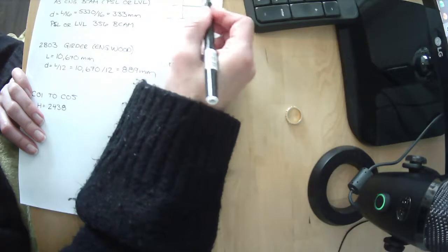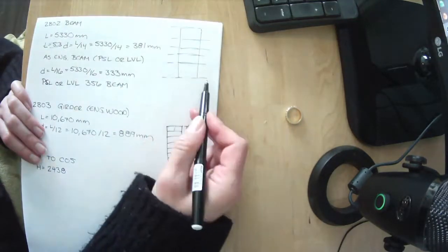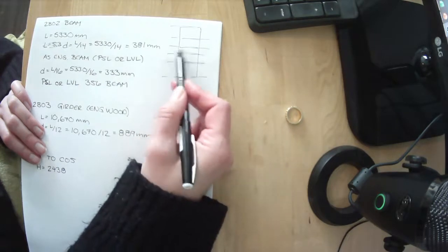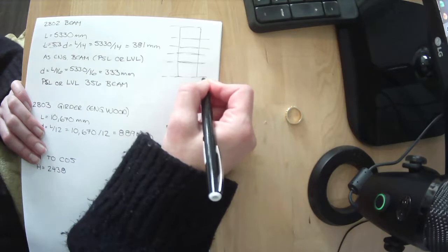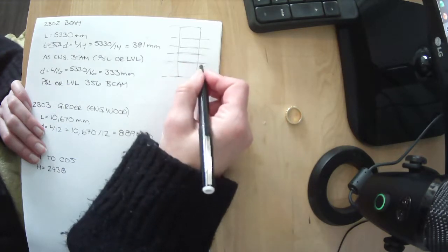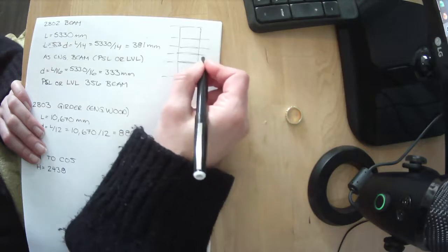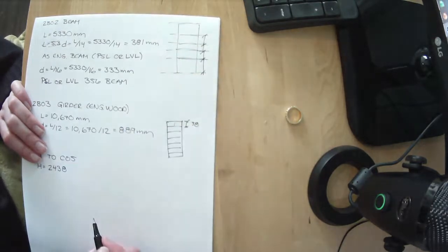That's a datum, that's a datum, that's a datum, that's a datum, and that's our ground. And then each one of these is a datum. Sometimes they'll refer to it from 0 and name off the datums, or they'll refer to them as a floor-to-floor height. But what we're measuring are these values here, which is our story-to-story height.